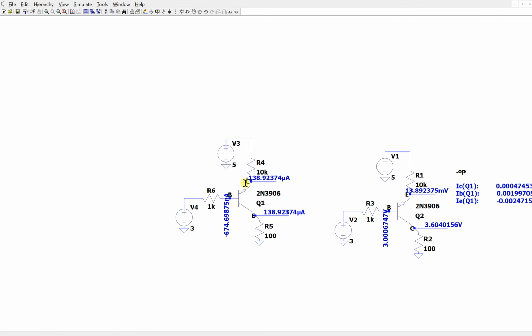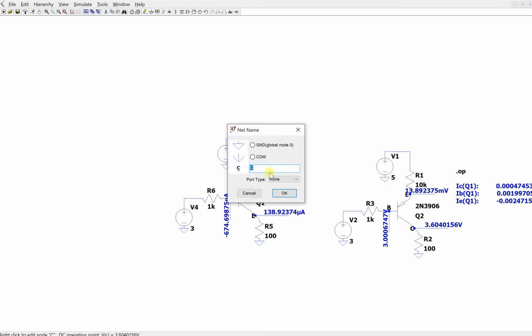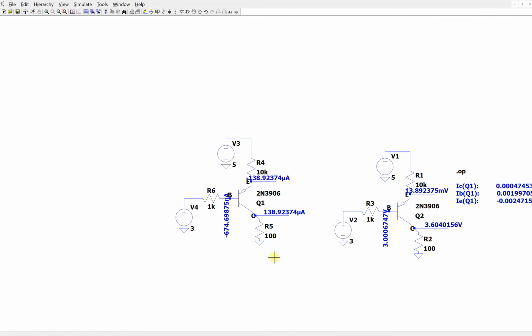Same thing for the copied circuit. The C will become the emitter in the PNP, and the E will become the collector in the PNP. You will just have now to run the circuit to get the results, since we already annotated the emitter, base, collector voltage and emitter, base, collector current. This pre-lab is easy, so make sure to do your best.